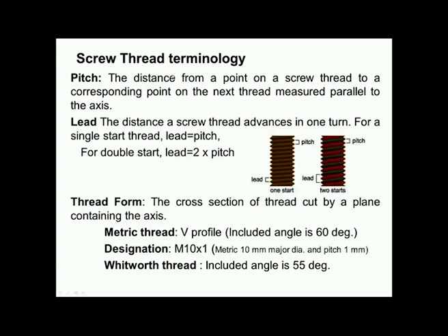Now, pitch is the distance from a point on a screw thread to a corresponding point on the next thread measured parallel to the axis. So, this is very important. When we measure the pitch, measurement should be made parallel to the axis. Now, you can see here this is a single start screw thread, wherein lead is equal to pitch.